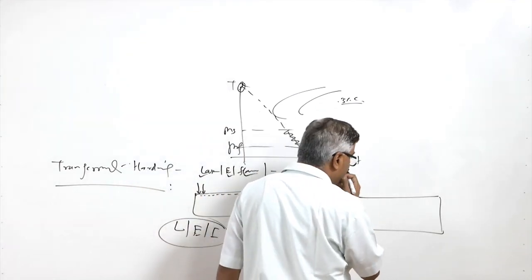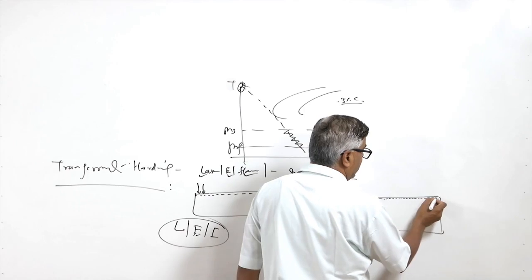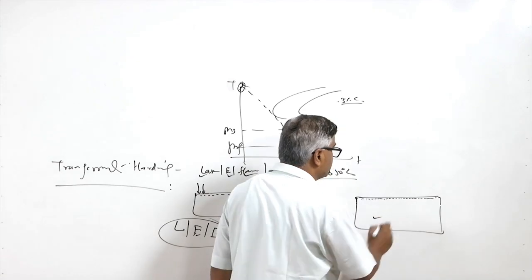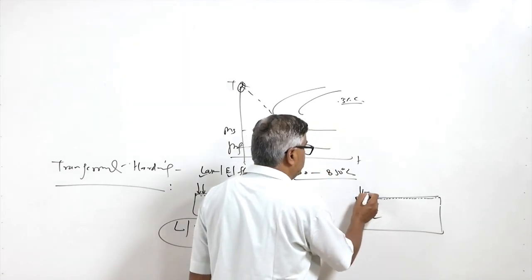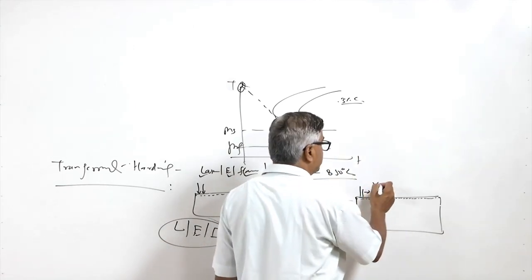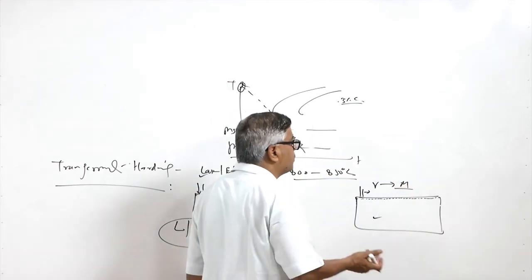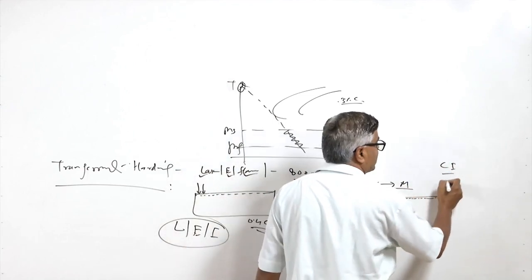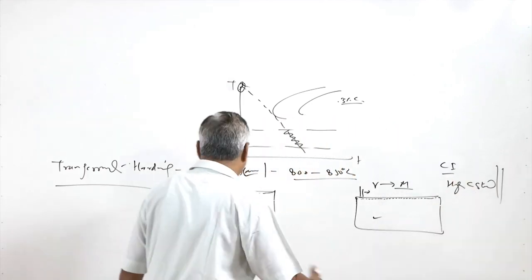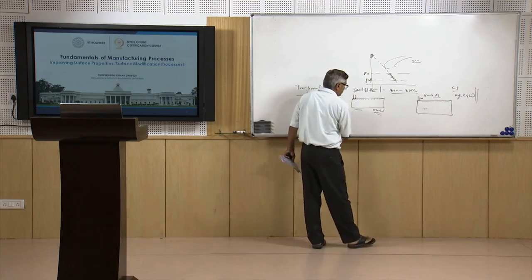What we do basically is that a very thin layer is heated to the austenitic state, and since it is in good metallurgical and thermal contact with the base material, as soon as the heat source passes, these zones experience a higher cooling rate from the austenitic zone and get transformed into martensite. For improved hardness and wear resistance, this is normally applied for cast iron and high carbon steels, for components like crankshafts and other components which will be under metal to metal contact wear conditions.